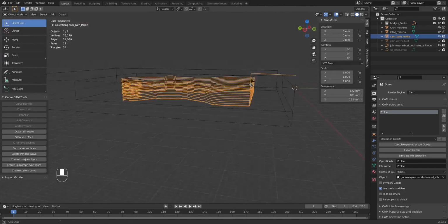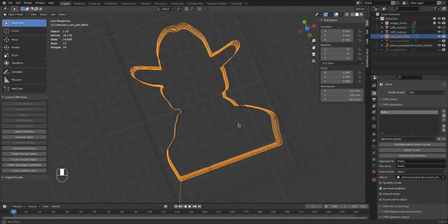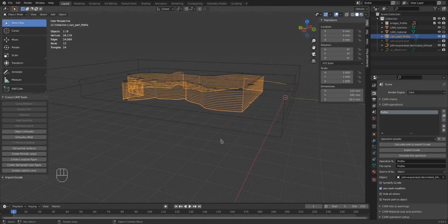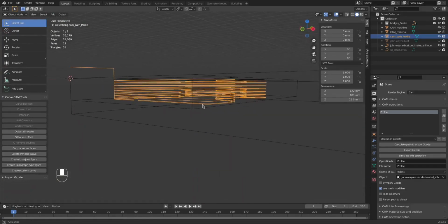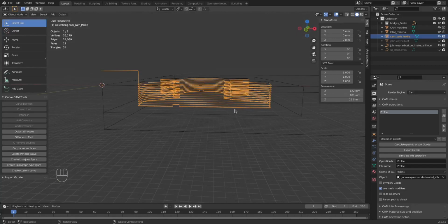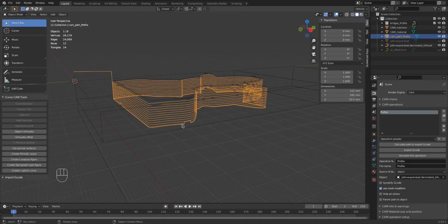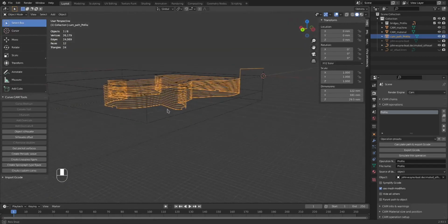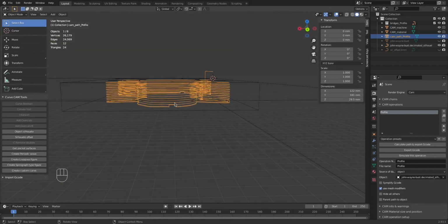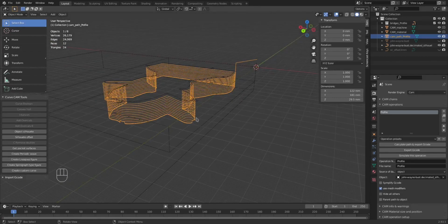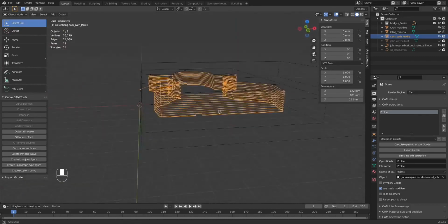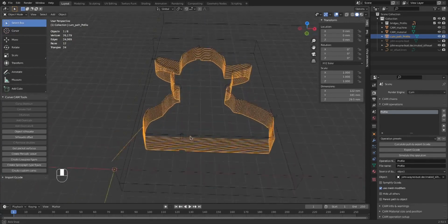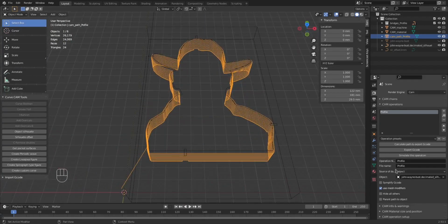We're starting off at Z0, working our way around this silhouette, taking about 1.5 millimeter steps down, and you see it miss the bridges here. It skips over right there. Like I said, those bridges, they'll hold the model to the material while it cuts. That operation looks good. We're going to move on to the next one.